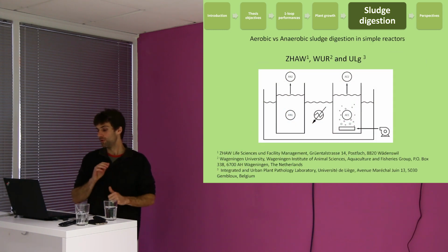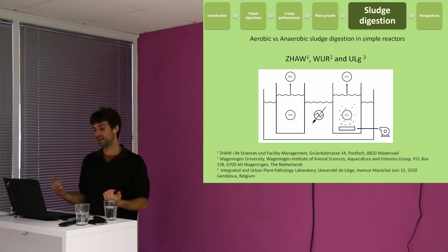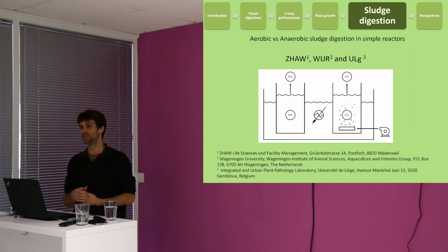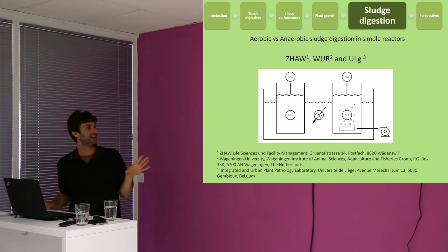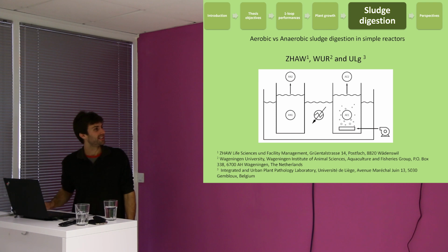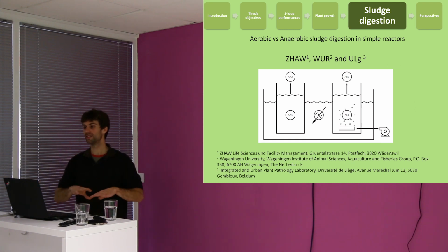To do it very low tech and simple on the aquaponic side, you have 2 solutions: you do aerobic digestion or anaerobic digestion. We tested both and we compared. So here is the bioreactor we used, very, very low tech actually. The anaerobic one is just a bucket where you put the sludge and you let it settle at the bottom, and it gets anaerobic.